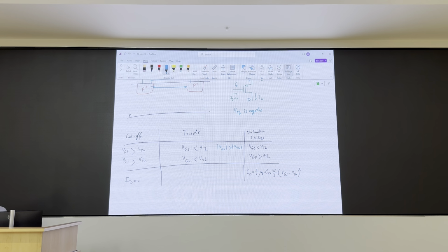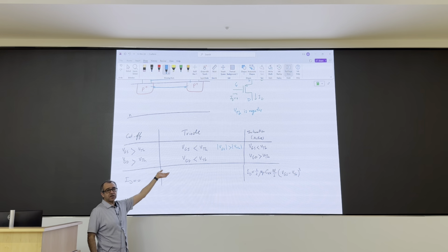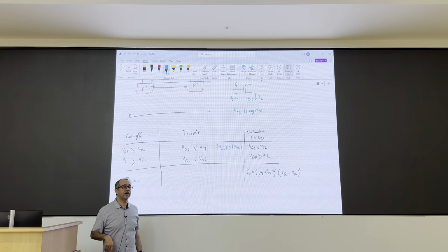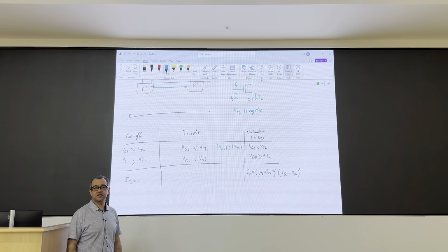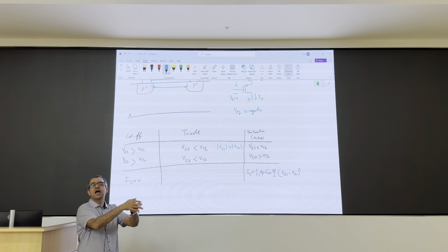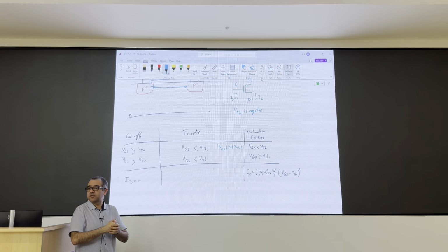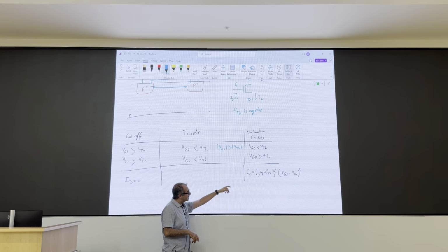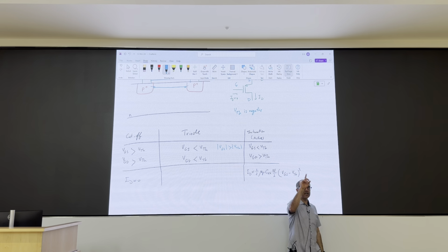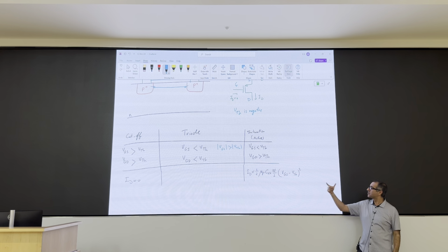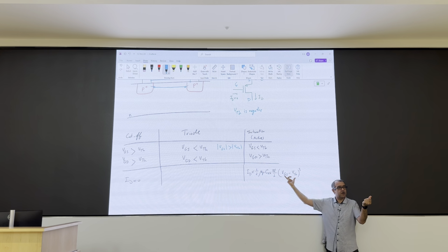That makes sense. The reason they do that is that this becomes similar to what you have for an NMOS. I don't like that because I think that absolute value can create some unnecessary uncertainty. Just keep in mind, VTH is negative, VGD has to be less negative or more negative depending on whether you want to have a channel at that end or not. And same thing for VGD. And then in this equation, for an NMOS, you have a VGS that is larger than VTH. So this VGS minus VTH will become a positive number. So it's 2 volts minus 1, so that's 1.